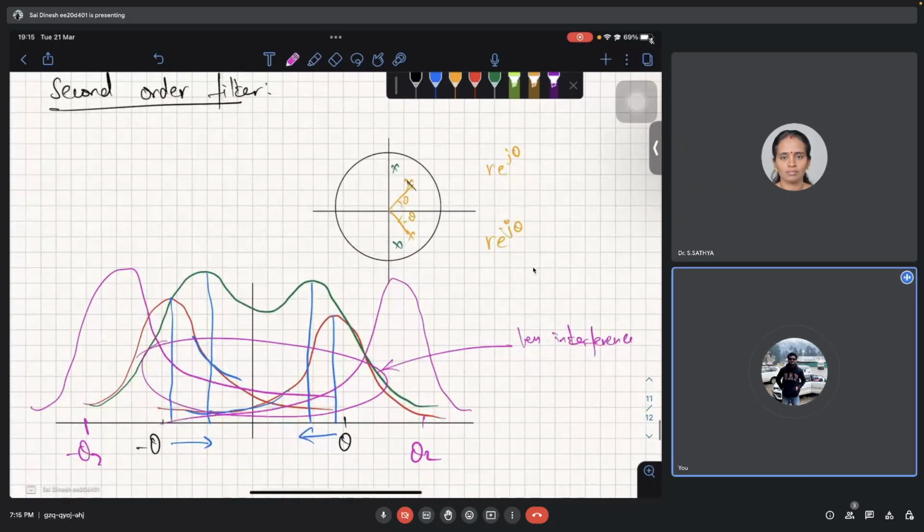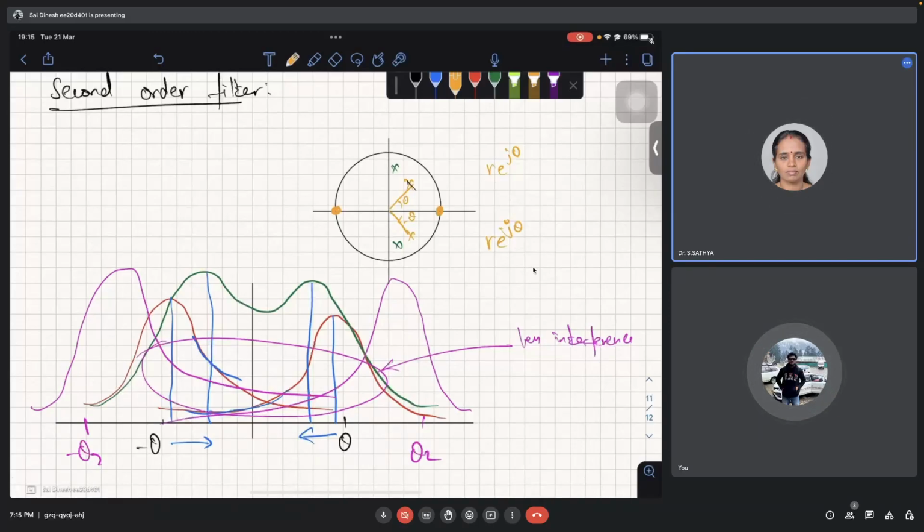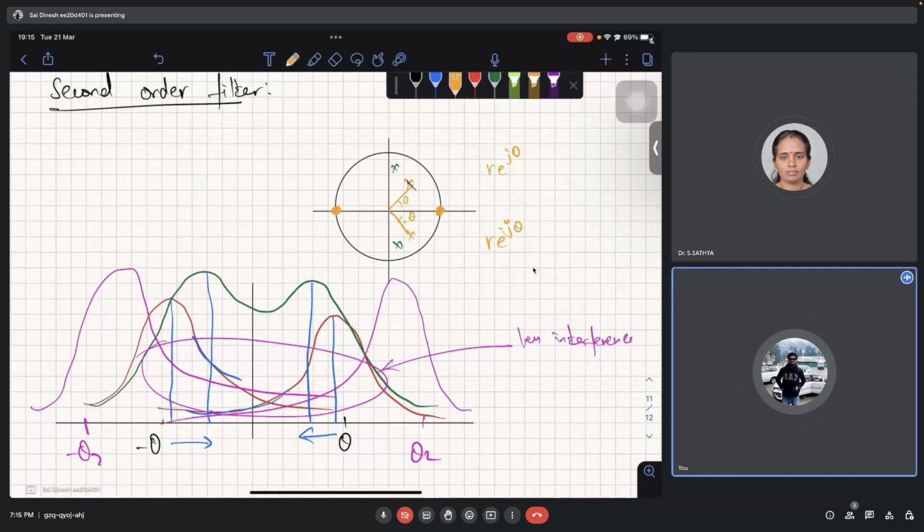Basically, this actually is the concept of peak shifting, but the improved resonator actually has two zeros and two poles. So because of two zeros, this is at the low frequency, and this is at the high frequency. Because of the improved resonator, there is an attenuation at low and high frequencies, right?